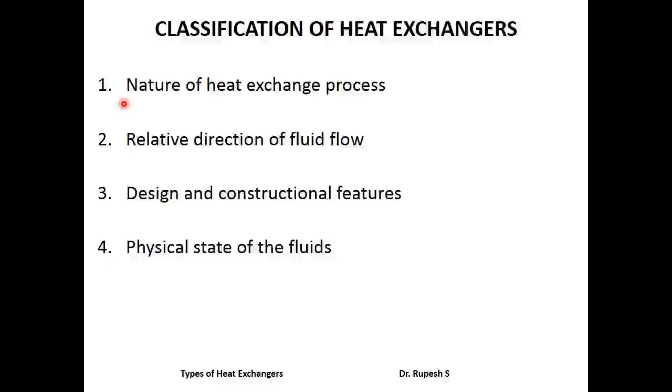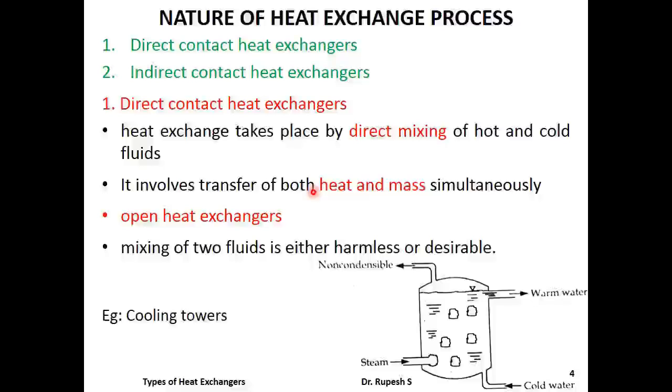Heat exchangers are classified based on nature of heat exchange process taking place in the heat exchanger, relative flow direction of fluid in the heat exchanger, design and constructional features of the heat exchanger, and physical state of the fluid in the heat exchanger. Based on nature of heat exchange process, heat exchangers can be classified into direct contact type and indirect contact type. We start with first one, direct contact heat exchangers.